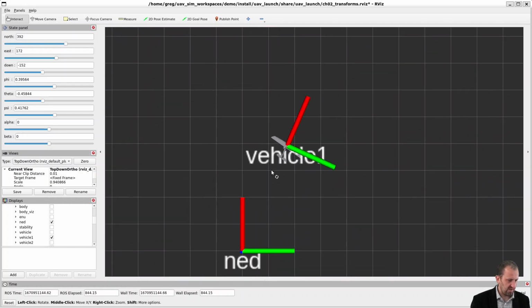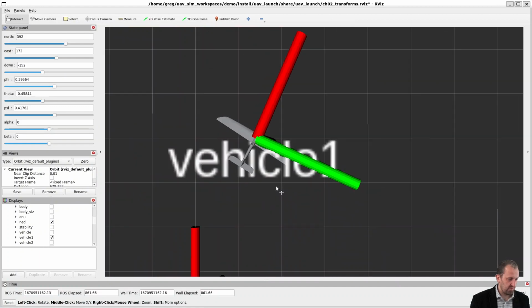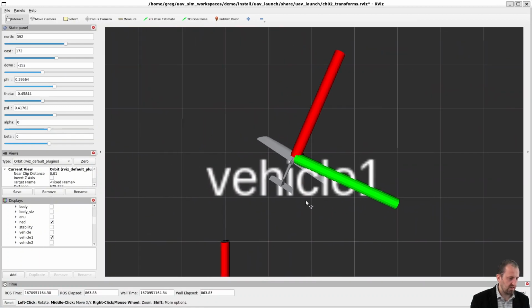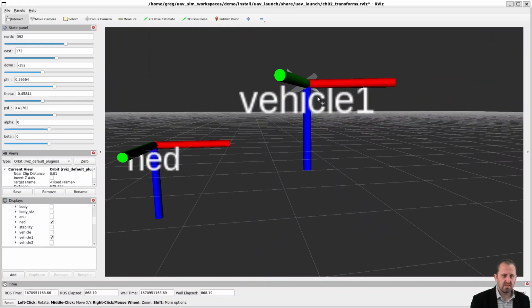Again, now if we have a top-down view, we've just projected everything into that northeast plane, and that vector now aligns with the direction of the nose in that northeast plane. And I want to make sure it's very clear that it actually does not align perfectly with the nose. If we take a look, the x-axis here in red is not pointing out the nose. It's the projection of the nose in that northeast plane.